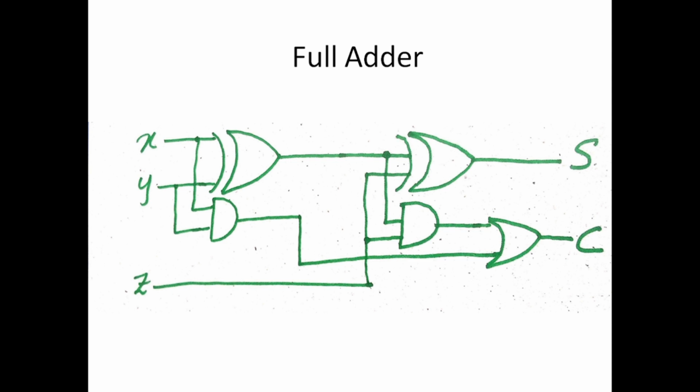This is a full adder. We had already talked about it. This full adder has been implemented using exclusive OR gates. We had already shown how to implement a full adder from typical AND and OR gates to exclusive OR gates. This implementation is quite compact and quite useful to analyze or investigate carry propagation in an n-bit binary parallel adder. In this full adder, we already know X and Y are the 2 bits that this full adder adds, along with an input carry, which is Z, and it produces a sum bit and a carry bit. I will use this description of the full adder in further investigation.